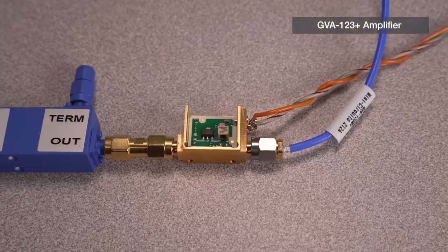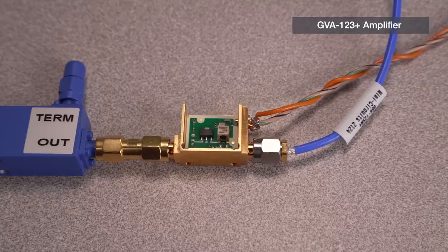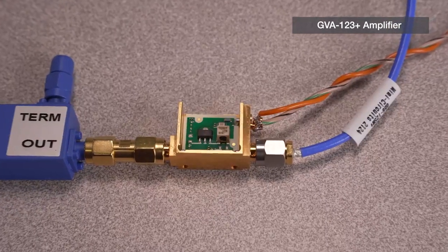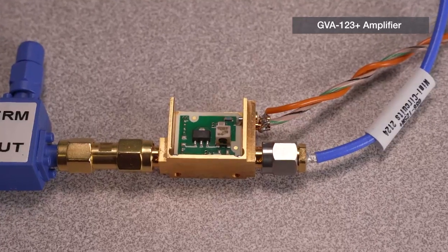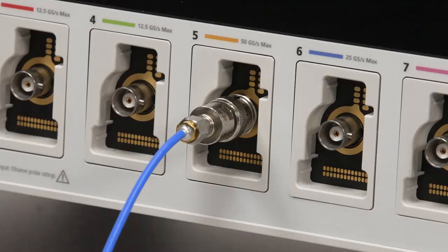For our device under test today, we have a GVA 123 Plus from Mini Circuits, a small scale amplifier, but it illustrates the measurement issues typical for user equipment and base station infrastructure applications. We are using a ZDC-10-01203-S Plus coupler, capturing the input signal on channel 1 at -10 dB down. The output signal from the amplifier is captured on channel 5 and is reading -0.8 dBm.